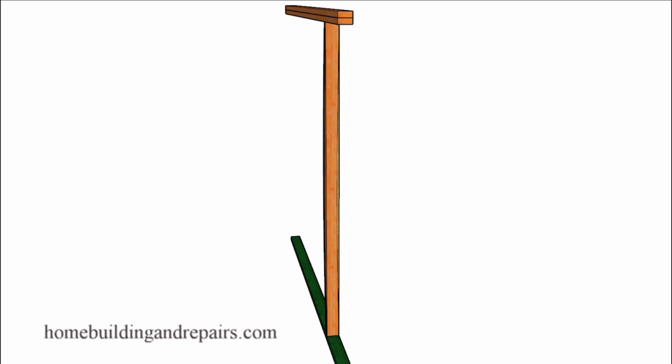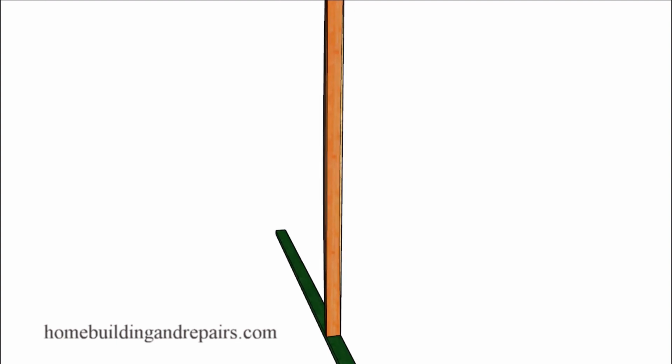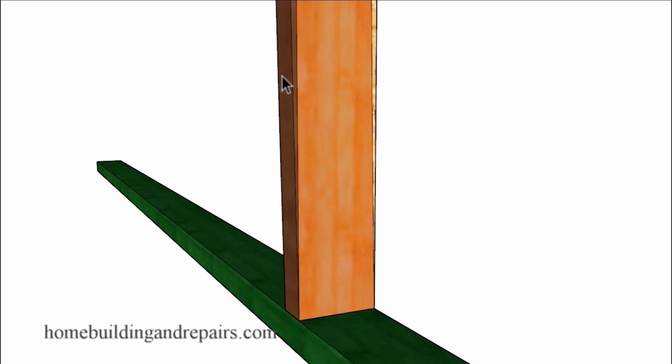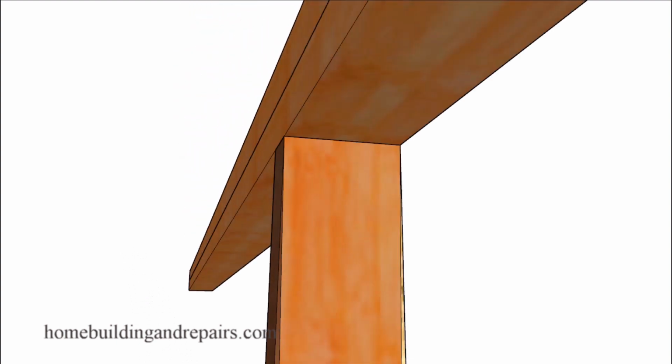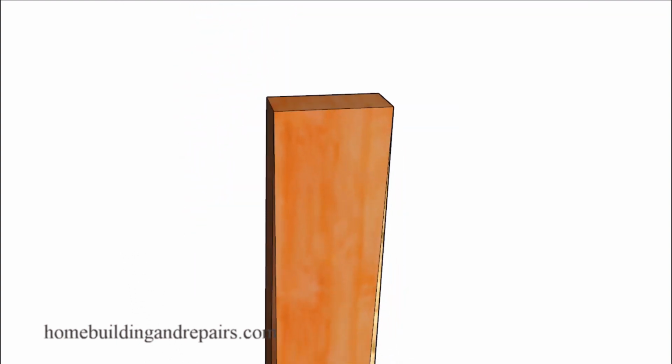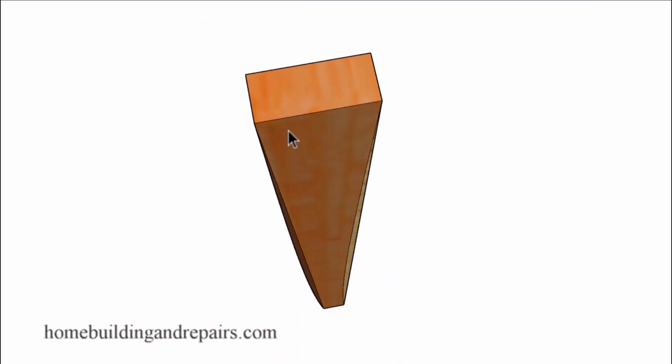And to straighten this wall framing stud, we're going to need to remove one side of the wall framing stud with a planer, which would be this area here, and we're going to need to add materials on the other side. And this is a common way of straightening studs. And I see carpenters using this method all the time, even when there are extreme cases where the studs are bowed more than an inch. And I'm here to tell you, you don't have to do that.